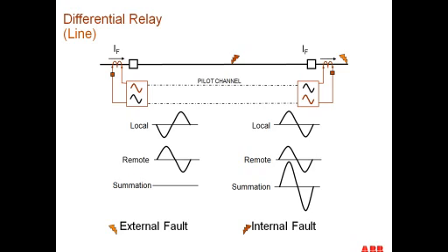Another question came up. What's the bus protection scheme, and how does the relay differentiate between a fault and switching? A question came up that said in a bus differential relay scheme, how does the relay differentiate between a fault and switching? I guess I don't quite understand the question, but any kind of a through fault that you would have, any kind of switching that you would have, would be seen as an absence of current, so you wouldn't get an operation at all.